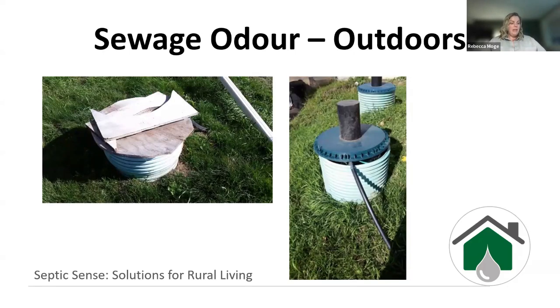Sewage odor in the outdoors. So often a cause from this is, again, if it's maybe surfacing in the yard, but we don't have a proper lid on. So these are two photos. The one on the left, obviously not a proper lid. And then the second one, this person was having issues and they dropped a pump in and then just started discharging it onto their property.